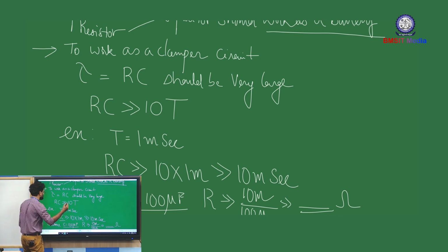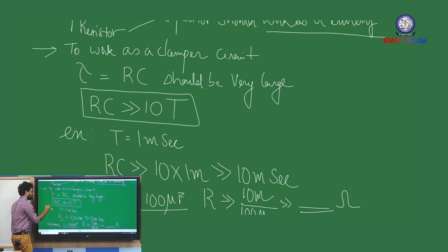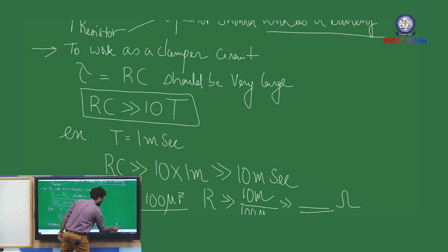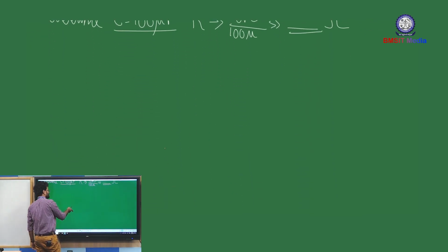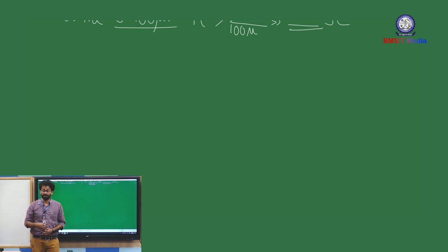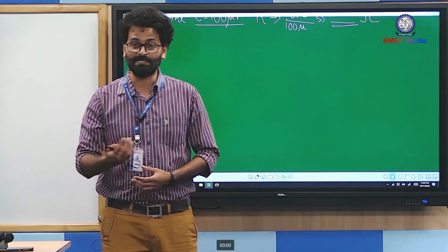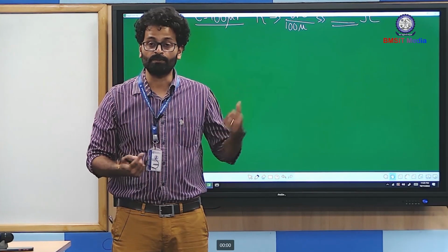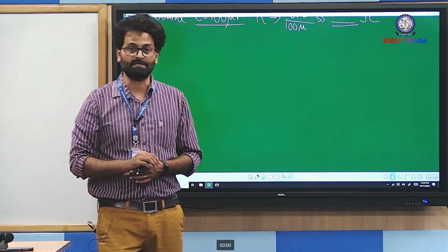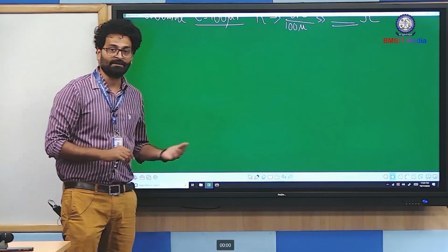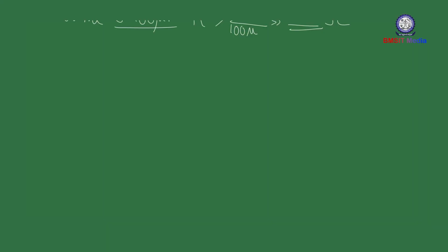The values of R and C are selected in such a way that the time constant of the circuit is maintained very, very high. Once we ensure this condition, even if the capacitor tries to discharge during a half cycle of the input waveform, due to the high time constant the capacitor will not get discharged, which is analogous to a DC battery condition.